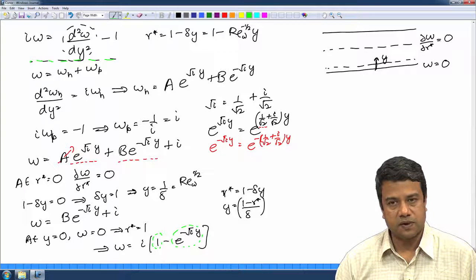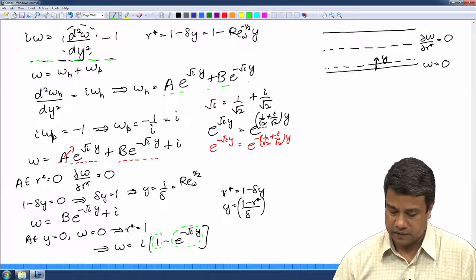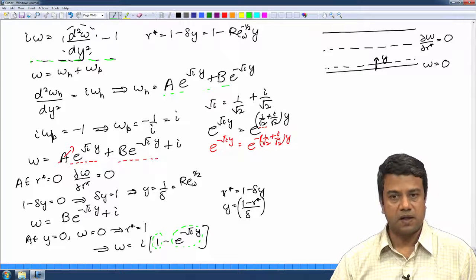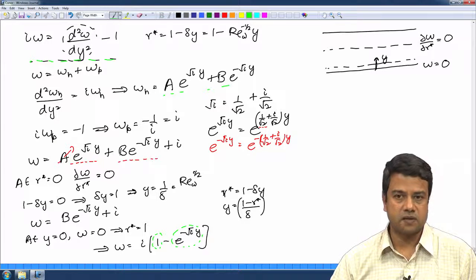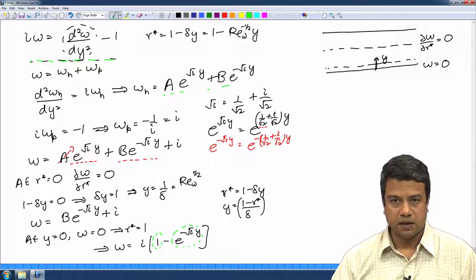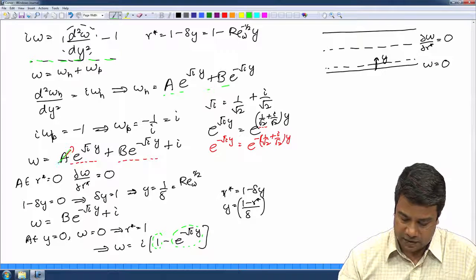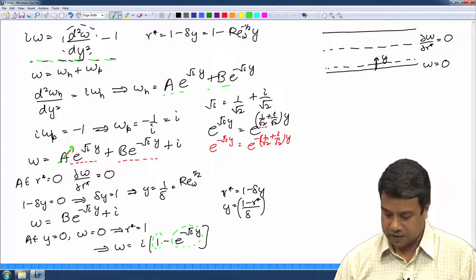Therefore, it is now possible to satisfy boundary conditions. In the homogeneous equation, we get constants of integration. The velocity disturbance is due to the wall itself; in the bulk the velocity is a constant. Very close to the wall, the retardation effects slow down the velocity within a distance of order delta from the wall. That velocity disturbance has to decrease to 0 as y goes to infinity. That gave us that one of these constants is 0, and the 0 velocity boundary condition at the bottom gave us the other constant.